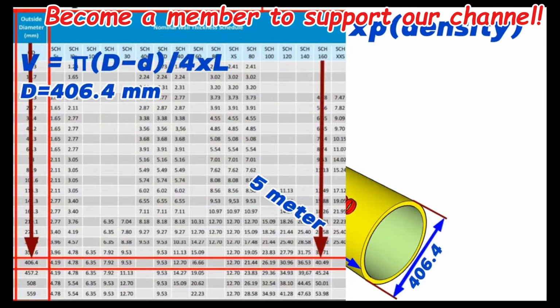Now let's write this information in the volume calculation formula. The volume of the 16-inch pipe in our example will equal 3.14 multiplied by, in brackets, 0.406 squared minus 0.325 squared, divided by 4, multiplied by 5 meters.